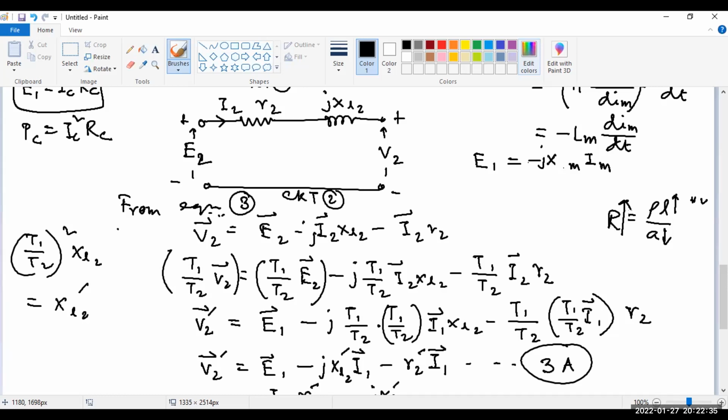So there is a difference in their nominal values. So R1 and R2 are completely different in this case. Now, from the design itself, if we try to relate that, then we will find that R1 and R2, their values are related by their turns ratio square.